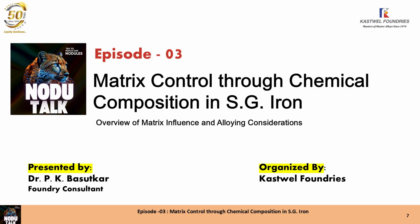Now, it is clear. We have seen the role of composition in the first two episodes. The base metal should be around carbon 3.8%, silicon 1.2 to 1.4%. This is base metal before the magnesium treatment. Then final casting composition: carbon around 3.7%, silicon 2.3 to 2.4%. Manganese, I would like to always have 0.3 max. You can have a little bit more, but manganese 0.3 max. Copper 0.25 to 0.35%, sulfur 0.02 max, and phosphorus 0.03 to 0.04 max.